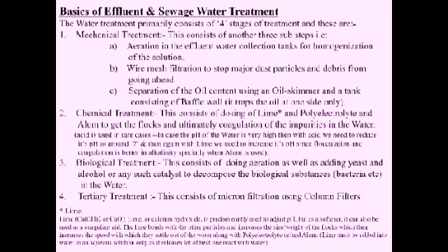Lime must be added into water in an aqueous solution only, as it has a tendency of releasing a lot of heat once it reacts with the water. So you need to take a little precaution. The person putting the dosing chemicals into the dosing tank needs to